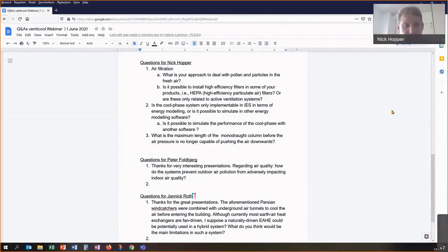So for our natural ventilation systems, when we're operating in natural vent, we don't have filters. When we're operating in heat recovery, we have a very coarse filter, and that's there to prevent the blockage of the heat exchanger core. And that works very similar to natural ventilation. Our terminals are very similar to openable windows. So, that's the context we have.